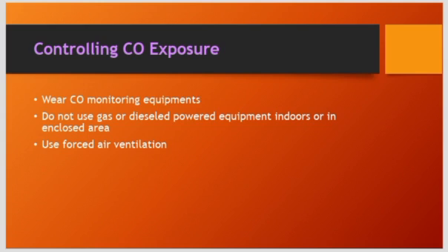Then, controlling CO exposure. Always ensure you wear your CO monitoring equipment, because you cannot perceive it, and it does not have any odor for you to identify that it is present. So it is best you are always protected, wearing your monitoring equipment, especially if you are working with machines that use gas, diesel, and propane.